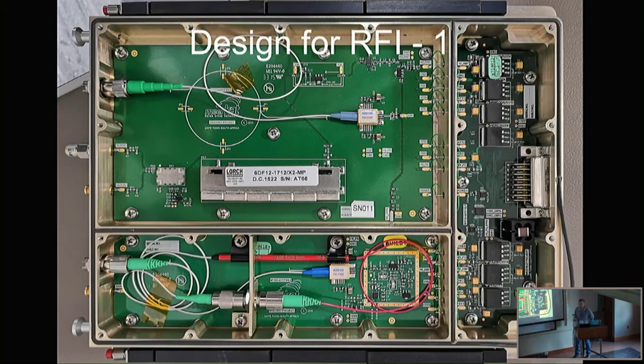So you start off on the schematic before you even get here. You think about RFI every single step of the way. If you don't need a clock, you don't design it in. It means compromises. Sometimes you have to run things at a slower speed, but you start there. Then the next step is you design the printed circuit boards with everything that you can shielded between layers of ground planes. And you carry on.